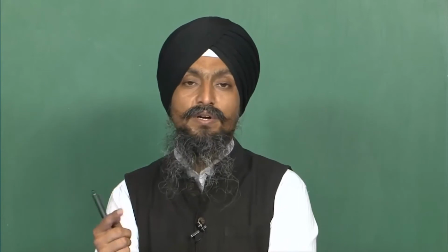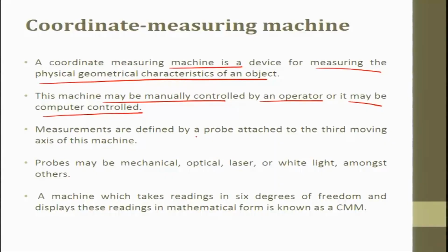We just give the initial point, okay, this is the starting point. Now, after each mm or after each 2 mm we can give that distance. It will record the points on a specific plane or specific curve, or we can change the direction of our probe. Those things can happen. This is CNC control. Manually also, using a joystick, we can keep touching the probe to control the data.